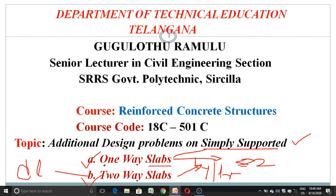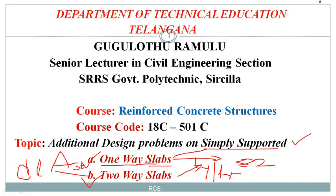After knowing the depth, we go for calculation of the area of steel, Ast. Ast can be calculated using the moment of resistance formula with respect to the tension in the one-way slab: Mu equals 0.87 Fy Ast into 1 minus Fy Ast by fck b d, multiplied by d. From that formula we can calculate the area of steel. After knowing the area of steel, we check with the minimum reinforcement required, then we go for spacing. The same applies in the case of two-way slab.